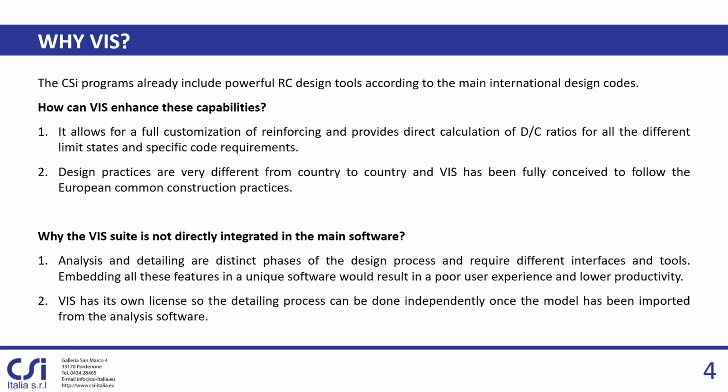Okay, so after this small introduction, I'm ready to answer the first question, which is how this can enhance the capabilities of the CSI program. Basically, because as I said, it allows for a direct calculation of demand capacity ratio for all the different limit states, which means strength, capacity design, serviceability design, and also detail and provision. And it allows for a full customization of the reinforcing. We will see it later.